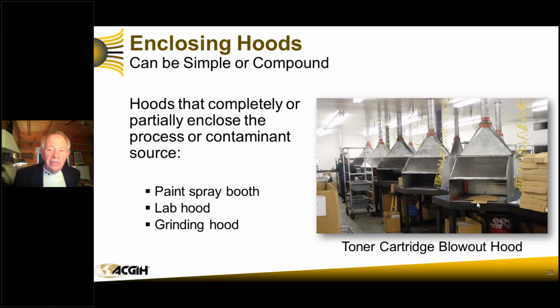Let's look at the simplicity of this. Our opening here is about, I'm going to say, I think, 8 inches by 2 feet, about 1.5 square feet. We did an inlet in-draft velocity of about 200 feet per minute. That 200 times 1.5 is 300 CFM. 350 CFM is 4,000 feet per minute in the duct. If it's a 4-inch duct, we can pull 350 CFM. We will pull 200 feet per minute through that face.